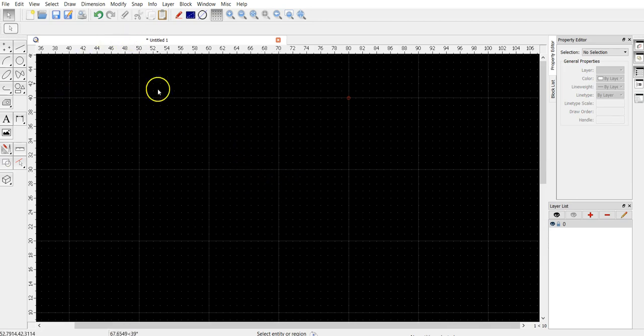One other thing that I'll point out while I'm designing in QCAD is I'm building everything off of reference points. I don't have to be at 0, 0 to design what I want, because when I take it over to the computer, it's just going to recognize what I've built in relation to itself on the screen. So you'll see that in action here, because I'm at 74 and 24 in open space.